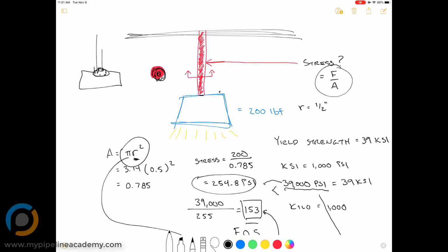Well, you don't see a rod connected to a lamp and nothing to connect it with. You're going to need screws. And to have screws, it's probably going to look like the rod. We have something around it that goes like this. This is going to be very thin. And then we're going to have screws on it, or like bolts right there. And then the lamp. This changes our stress, because stress is force divided by area. And our area has changed now. It's not this rod. It's almost like a thin sheet. And I was wondering how that would change. So hollow, and then make it this area here.